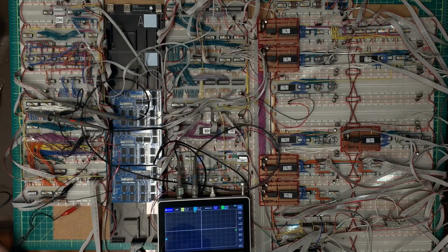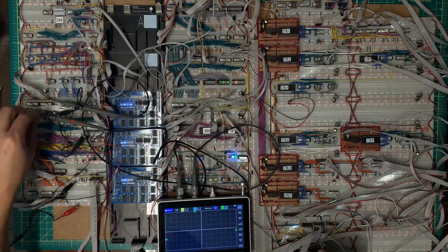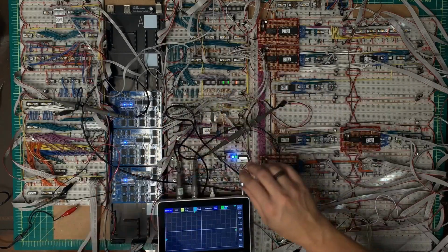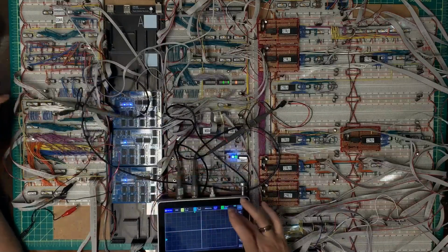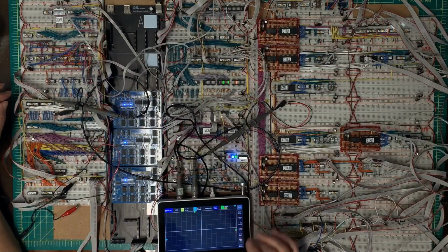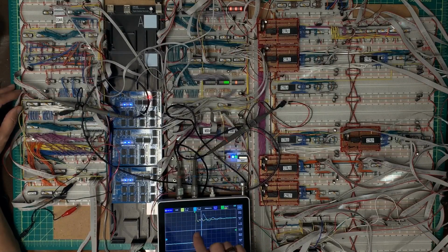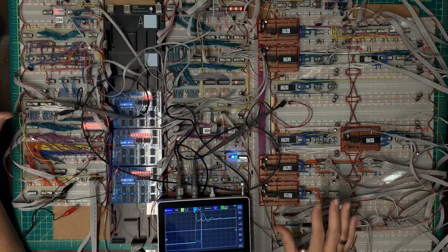Okay, before I go and take anything away from this, I figure it's probably better to spend a minute and make sure that I've got all of my signals sequenced properly. So the first thing is I want to take the clock and compare that to the latch. So I need to be triggering on channel 1, and I want the rising edge of the clock. So the clock is the yellow and the latch is the blue. And that looks like about 100 nanosecond delay. So that at least it should be in the correct sequence.